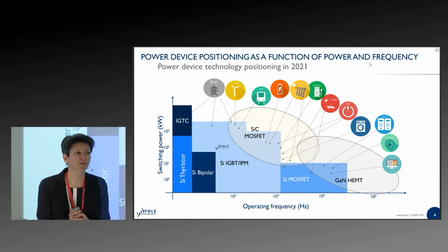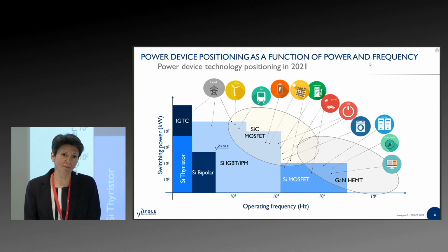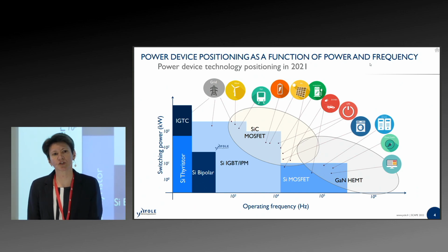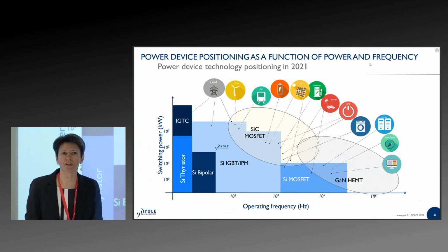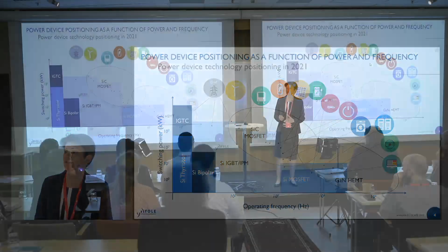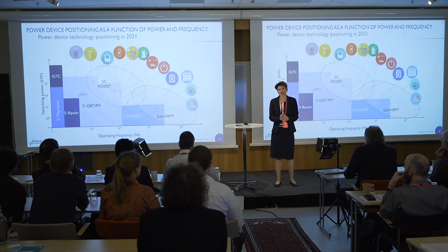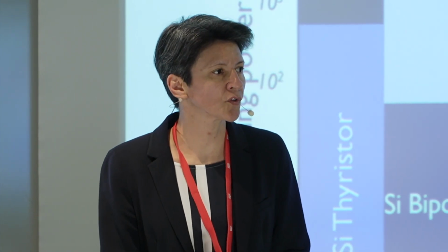And that's where you would have some sweet spots for this new innovative, disruptive technology, wide-bandgap silicon carbide and gallium nitride. Silicon carbide addresses more of these high power applications, while gallium nitride has more advantages for high operating frequency applications. And as we've seen in some of the talks also, there is a competition zone between the silicon offering, silicon carbide, and gallium nitride around 650 volts, where you could have a mix of the technology platforms depending on the requirements of your application.